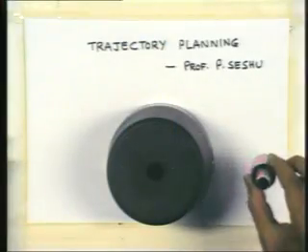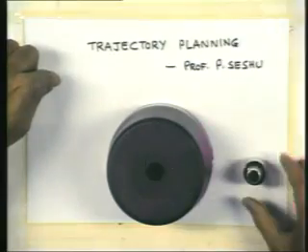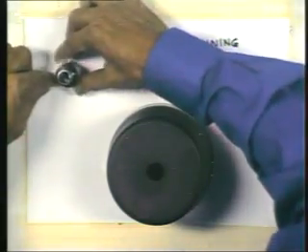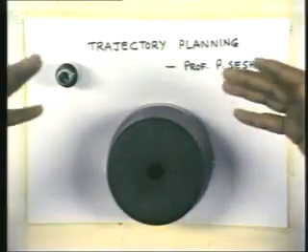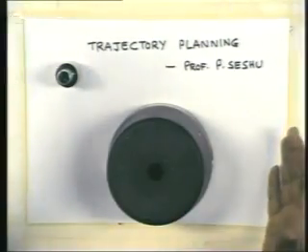Say, for example, here I can say that from point A I want to go to point B, but via a point C. So I want you to go roughly like this so that you avoid the obstacle. That is one way where I could specify a path indirectly through initial positions and final positions, but avoiding certain obstacles through what are known as via points. But in this whole process, the specific path taken between any 2 points is not of much significance. Okay, such types of tasks, such types of motions, are what are known as point-to-point motions.